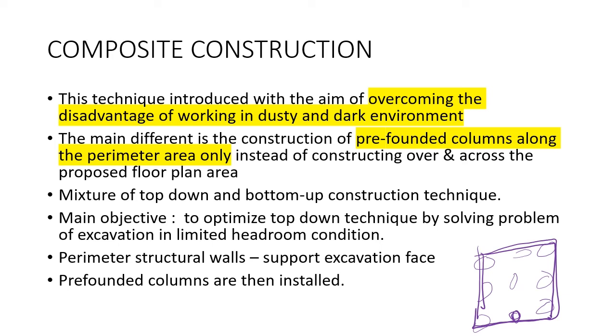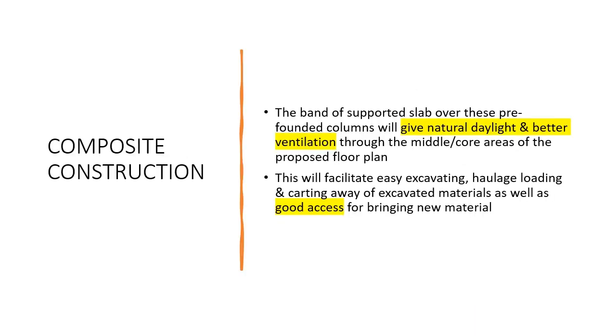Mixture of top-down and bottom-up construction techniques, and the main objective is to optimize top-down techniques by solving problem of excavation in limited headroom condition. The perimeter structure walls will support the excavation phase and pre-founded column are then installed. The band of supported slab over this pre-founded column will give natural daylight and better ventilation through the middle or core areas of the proposed floor plan. This will facilitate easy excavating, haulage loading and carting away of excavated materials as well as good access for bringing